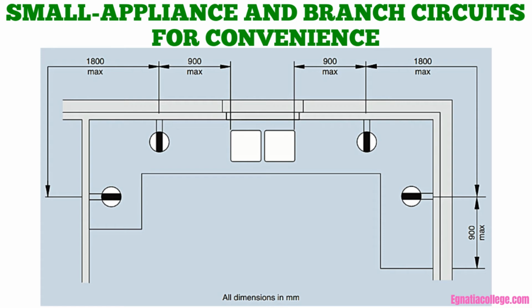Microwave enclosures must be supplied with a receptacle on a separate circuit, Rule 26-652. If no cupboard or enclosure is provided, the microwave would be powered by one of the countertop split or T-slot receptacles. All outdoor receptacles within 2.5 meters of the finished grade must be on a separate GFCI protected circuit, Rule 26-654E. Counter receptacles may be 15-ampere 3-conductor split circuit or 20-ampere T-slot receptacles.